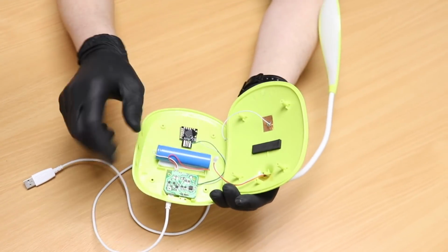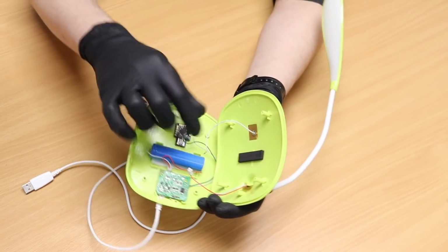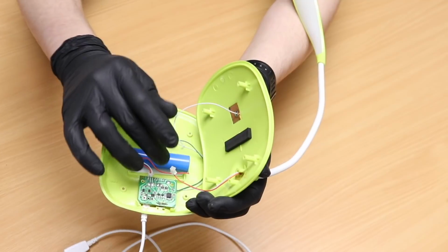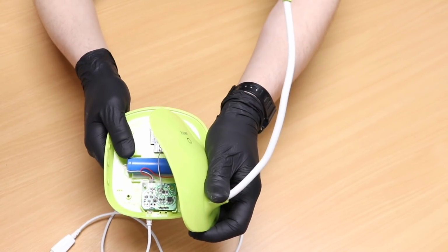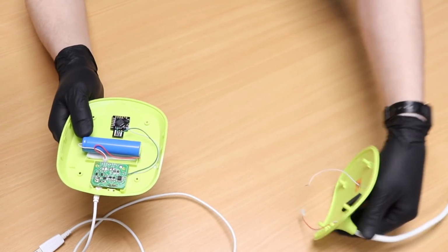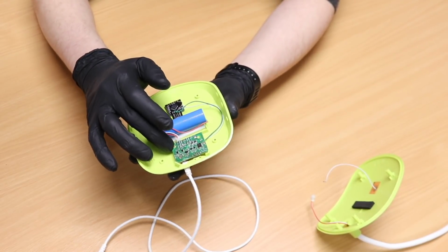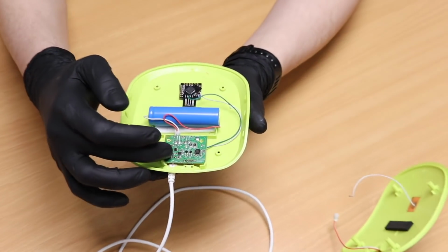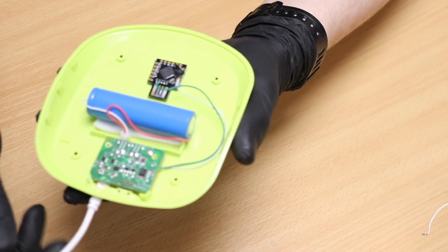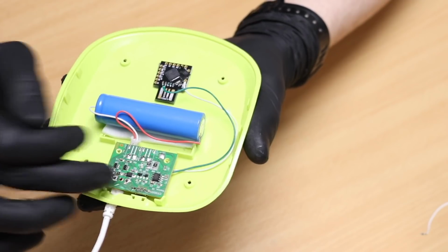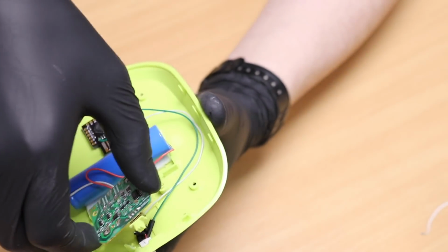And the top part is connected to the printed circuit board. This is for the main LED light, this here. And there's another wire that is soldered here, which is for the capacitive switch that allows us to turn the lamp on and off. So once we've done that, we can get to the main printed circuit board. Now it has two main solder joints connected to the USB cable. So we desolder these two with some wick and the soldering iron, and we can pull off the board.